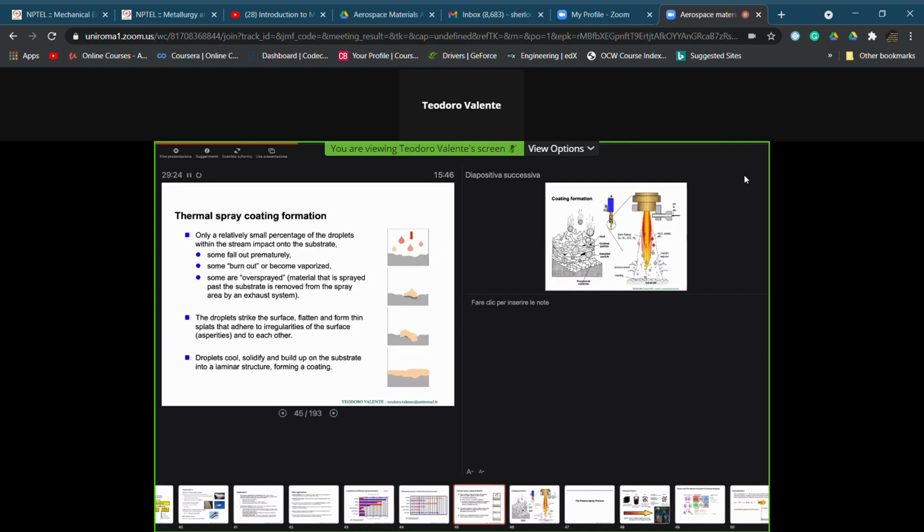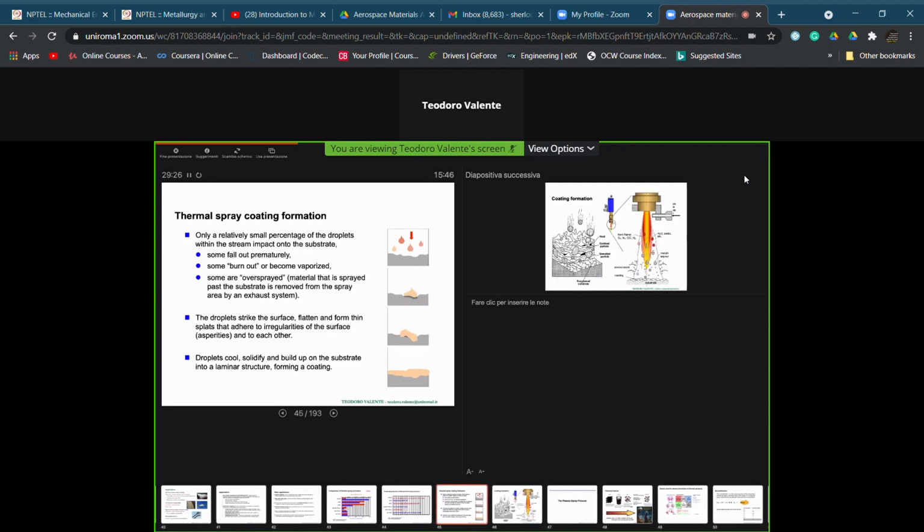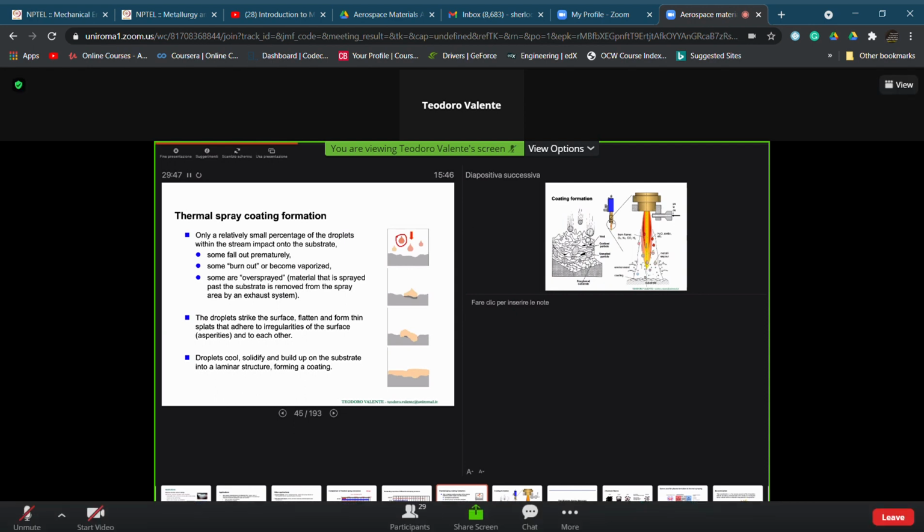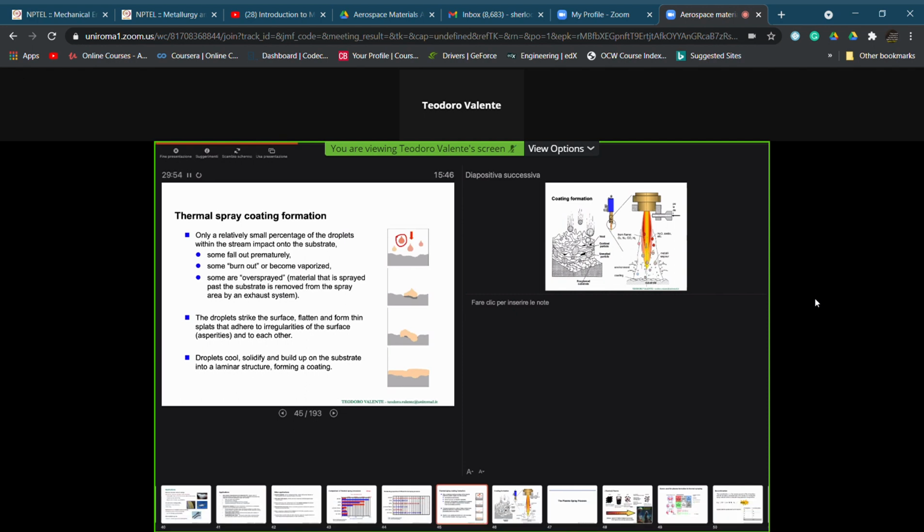How is the coating formed? These are, let me say, general concepts which can be used for both classes of technology. We do have particles, starting particles, powders. These starting particles must be selected in average size, but also shape, but let's talk about size, in a proper way, because you should have in mind your, let me call it flame, what is going out from our torch.